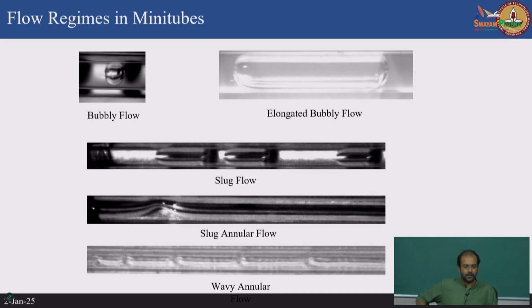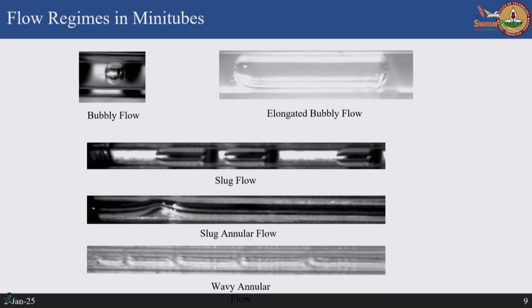Portion in flow boiling, which is basically the flow regimes in different size tubes, and then how we use correlations which are purely empirical, based on experiments, because there is absolutely no rigorous theory to calculate the heat transfer coefficient during flow boiling. Even in pool boiling you have seen that we rely on empirical correlations. So flow boiling is even more difficult to use any theory for.